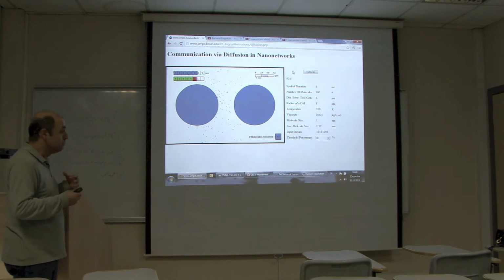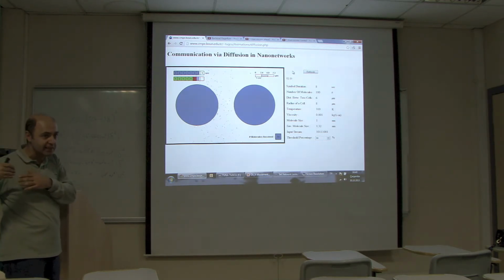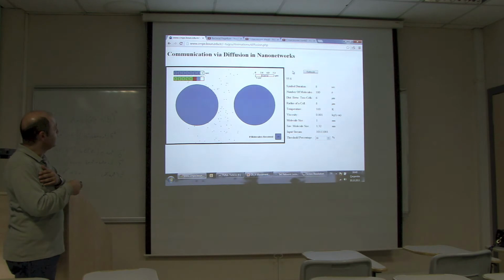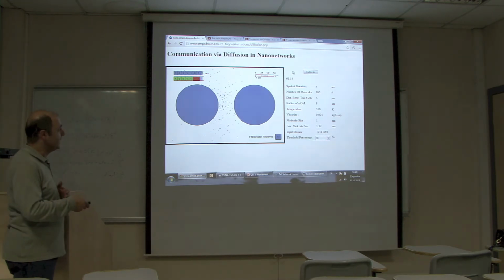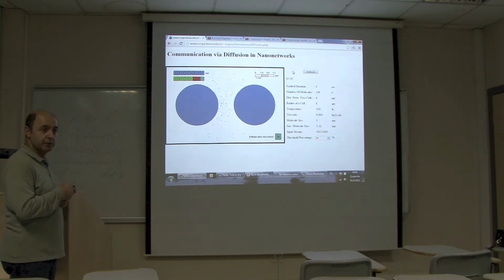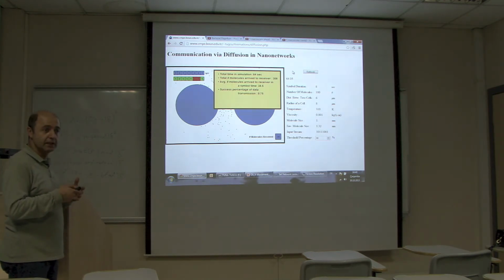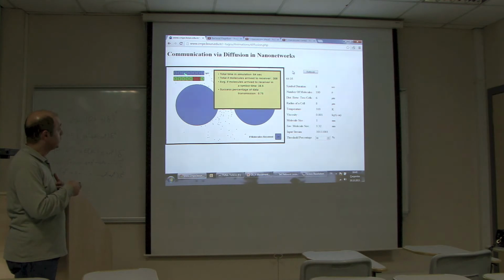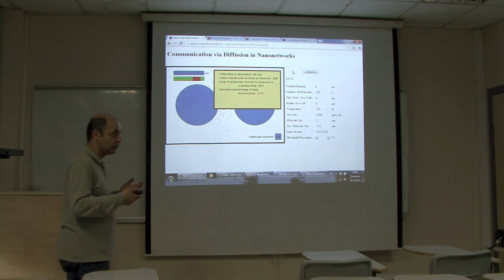Since many molecules were released from the previous symbols, they cause interference, intersymbol interference. Also another one here, 2 consecutive. And these 0s were misunderstood as 1. Now if you increase the threshold here, probably this will not happen. But then it's possible that some of these successful transmissions would be misunderstood. Like you could miss once if you increase the threshold.